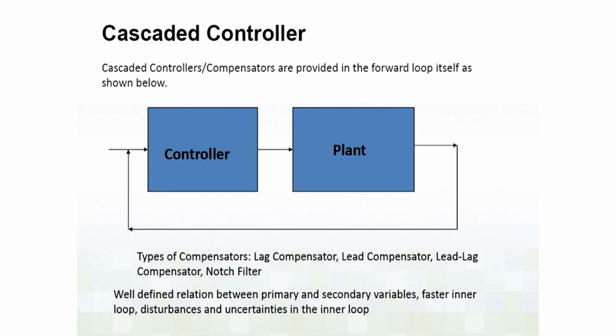If you remember, we have talked about a gain K earlier, and we have talked about the plant G earlier. Now, this gain K was a constant value that can be changed, but when we talk about a lead or lag compensator design, we will make it slightly more complicated. So, it will become K (S plus A) over (S plus B). That means the system can have a 0 as well as a pole, and all these things come not in the feedback loop, but in the forward loop. So, this part is the forward loop.